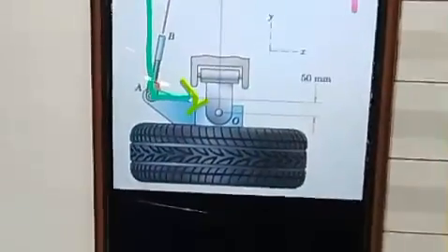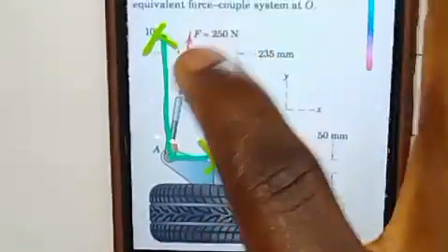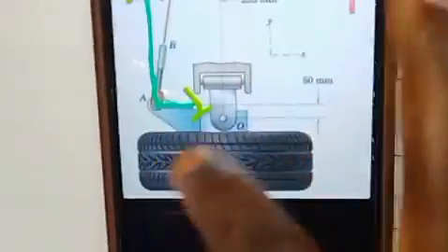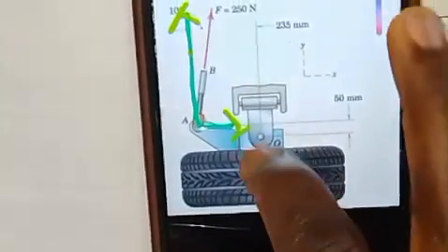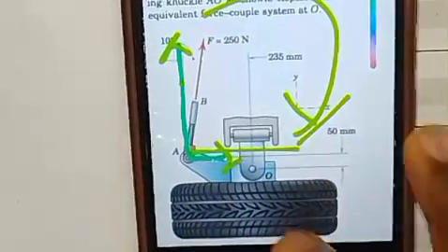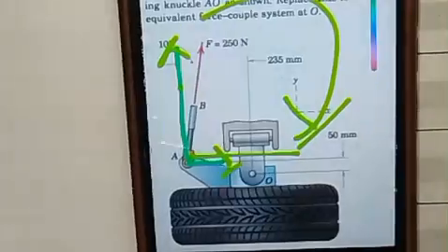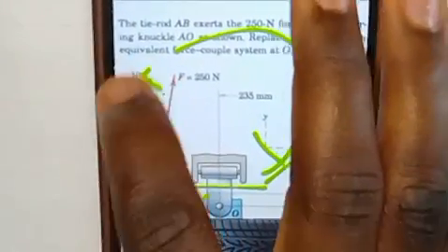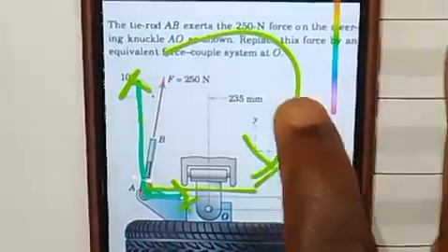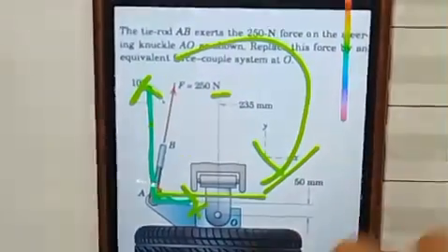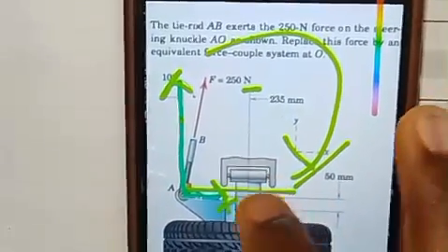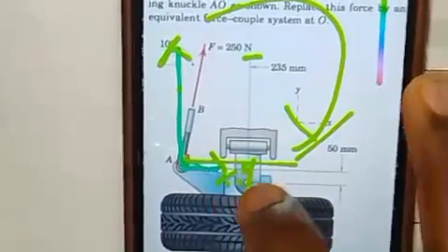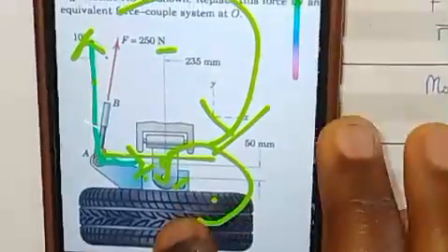So now if we resolve this particular magnitude of force into x and y component, the line of action of this force is here, and the perpendicular distance to this center here is this. So you take this particular force in this direction, so we are going in the clockwise direction rather. So your Fy times the perpendicular distance here, which is in clockwise direction, will be negative. Then also this particular x force here times the perpendicular distance here. So you will also be going in this sense.